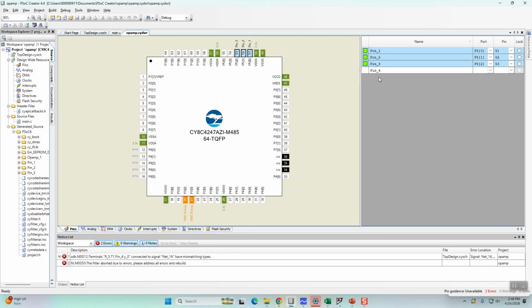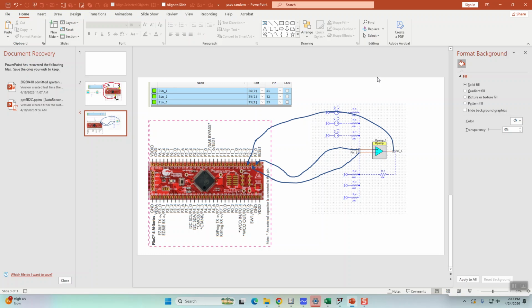This pin hasn't been assigned yet. Again, I have to fix that, but that's not the part of this video, is that you can make a 3 input digital to analog converter with an op amp, do some resistors here, and that I haven't shown you exactly how, but you can actually write your test vectors here rather than use the function generator.